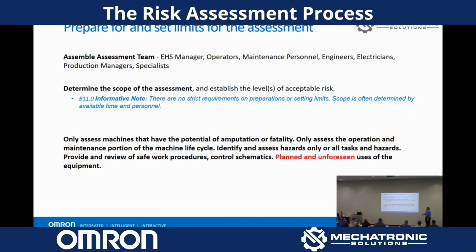Let's start there. Initially, only assess machines that have the potential of amputation or fatality. Assess the operation and maintenance portion of the machine life cycle. Don't worry about tear down, disposal. We've got to start somewhere.